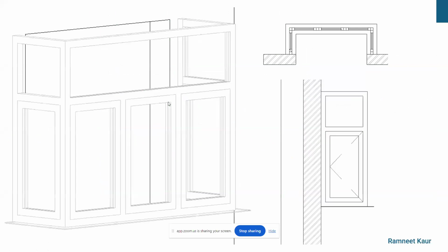This is a very quick example of how we can create window families and interesting families here. So this is a final look once it is done. Prakriti has already talked about loadable families. Window is a loadable family. So once it's loaded into the project, you can see how the plans come up, how your elevations come up, and how it will look in 3D. So any design which is customized to your projects can be easily included.